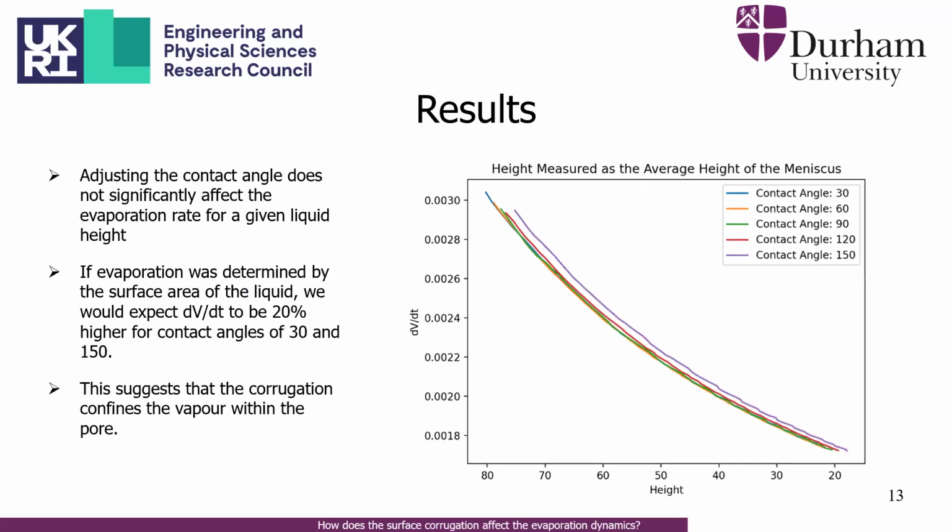Okay, now some results with this method. So we started looking at this geometry I talked about earlier. And as I mentioned earlier, for the kinetic driven evaporation, as you change the area through the contact angle, you'd expect different evaporation rates as you get away from a 90 degree contact angle. But for this case, this is showing essentially the total flux for a given height of the interface. No matter what contact angle you choose, it doesn't matter. So there seems to be no effect of the surface area of the liquid.